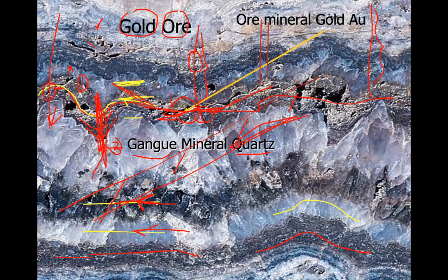So that means you should understand that from this hole to this hole, this length, this short length. In this case, it is short, but in the field it may be longer than that. There should be some layer extension in an angular way, right? So because of this depth difference, you can understand this layer is extending in an angular manner.